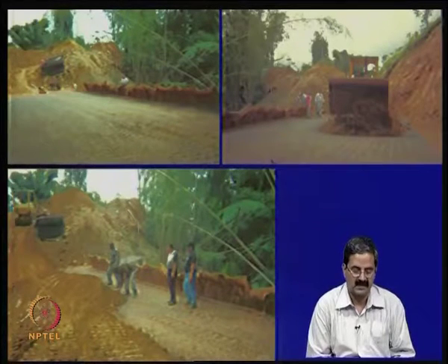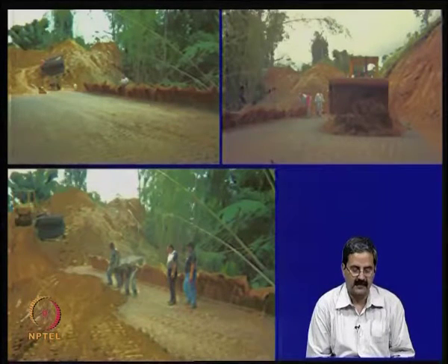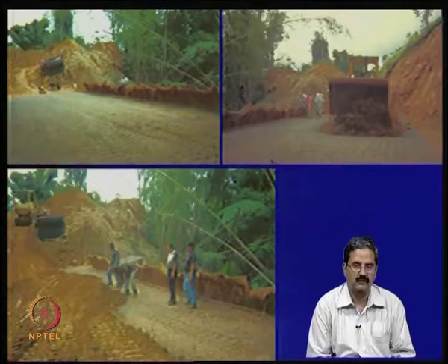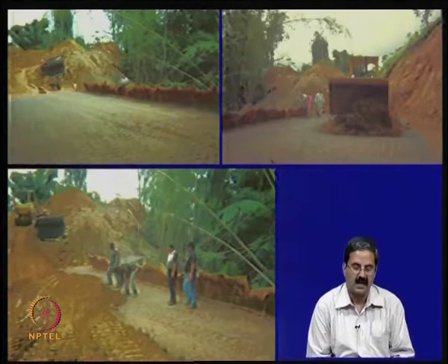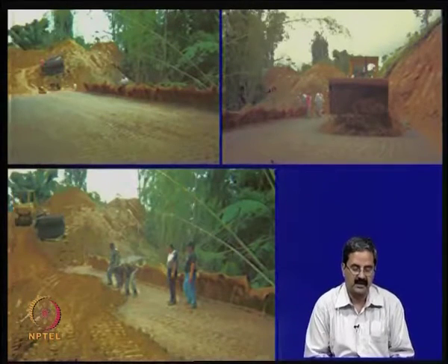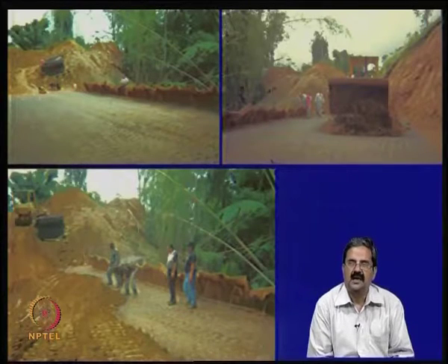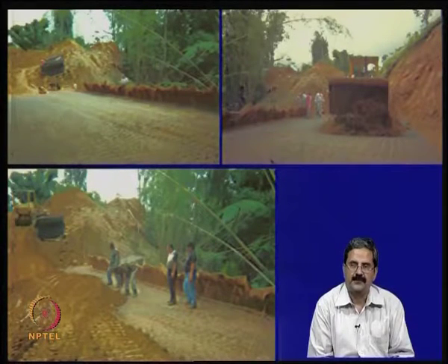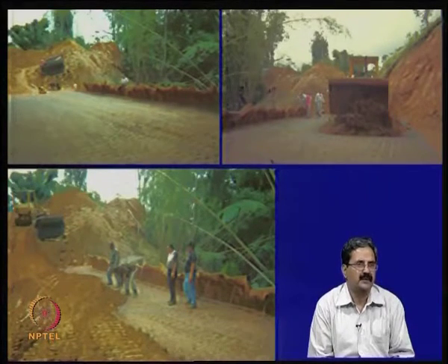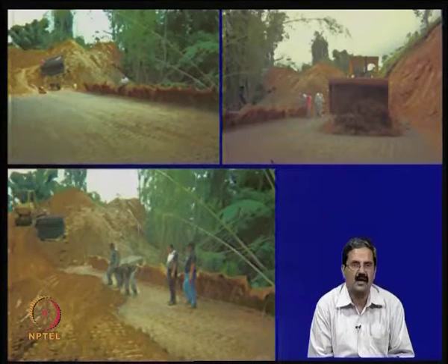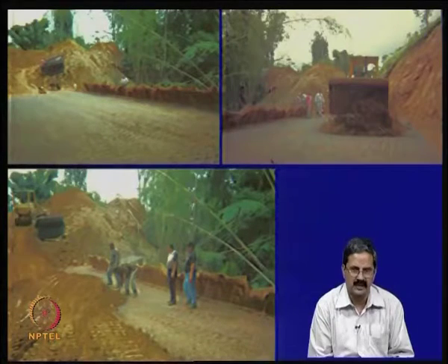It should have good density, because the objective is that it should have very good friction between the soil and reinforcement, and there should be very good drainage actually, because what I just showed you was that drainage is very important. Okay, I gave you the slope design for ru equal to 0, where the pore pressure coefficient is 0.